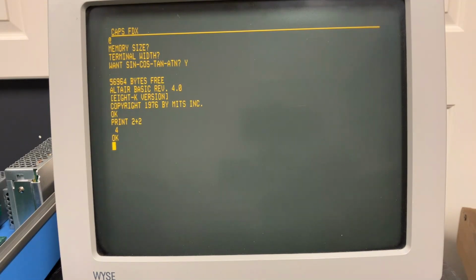And then in a silk screen on a later rev of the same board, it's the opposite of the manual. But all 3 of those appear to be wrong from what I can tell, at least for the version of the board I have. And my guess is that they're all the same as mine, where 1 is up, 0 is down. Now, if you do get this board, all I would say is don't trust the silkscreen, don't trust the manual. Make sure you take a look at that board and see how it's actually wired.